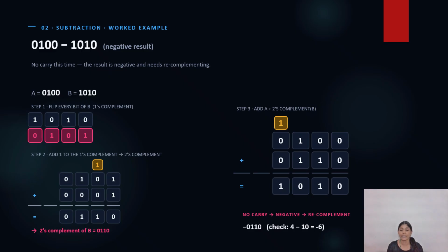After doing the binary subtraction also, what is the result we got? 0, 1, 1, 0. See, here also you have to take a 2's complement. Please don't forget. So 0, 1, 0, 1 you will get. Right? So you have to add 1 with the LSB. So 1 plus 1, 0, 1. So 0, 1, 1, 0 is the result.